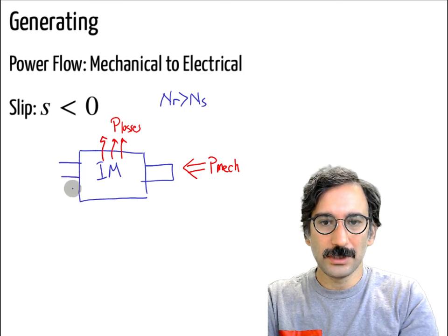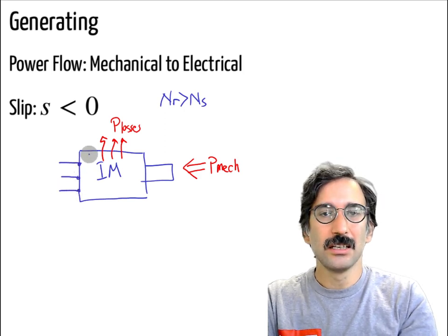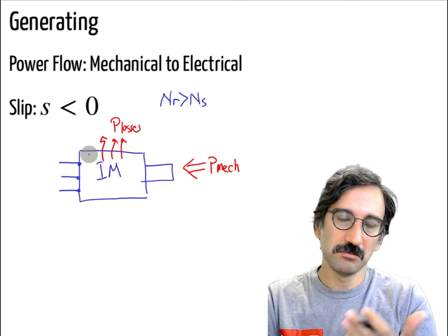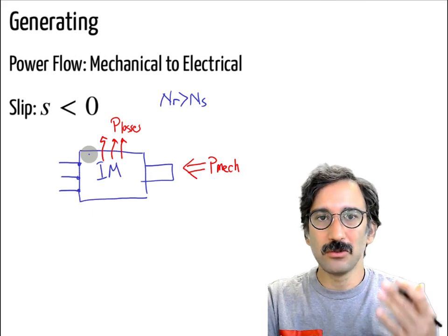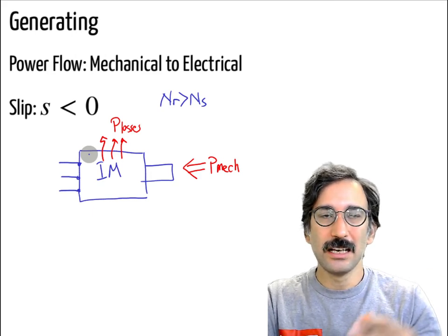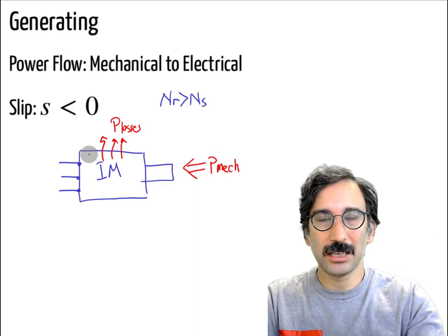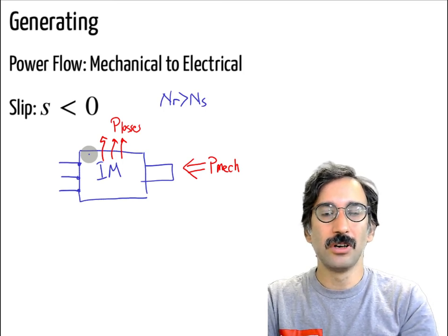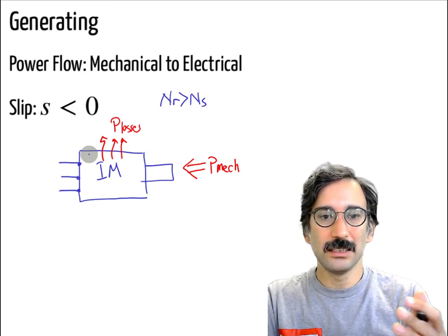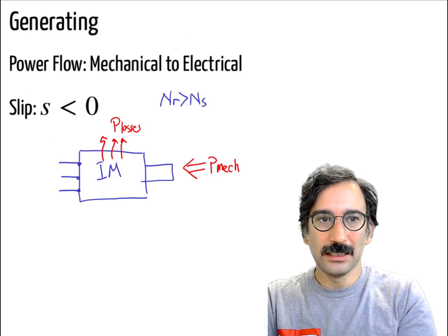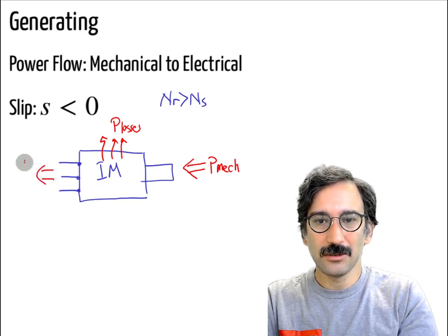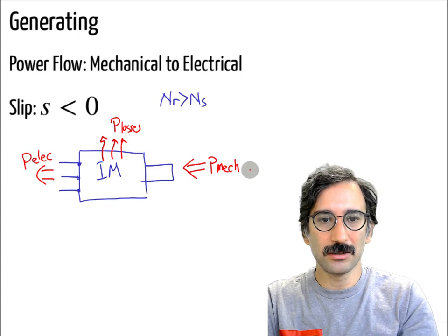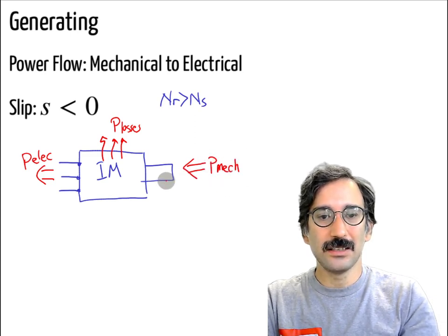I'm telling you that because in some cases, for the efficiency definitions, you can say, okay, output power divided by input power. Okay, that's fine. But if you just memorize the efficiency equations, like mechanical power divided by electric power gives the efficiency, yes, that is true for the motoring case, but if you divide the mechanical power by the electric power in this case, you will have efficiency larger than 100%, which is not correct because mechanical energy is now your input.